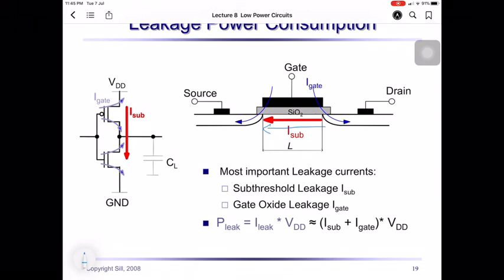A transistor is not supposed to turn on or create a channel at lower than threshold voltage, but here in this subthreshold region there is a small current that can still pass through before the channel is inverted. So this is known as I subthreshold or the I leakage.